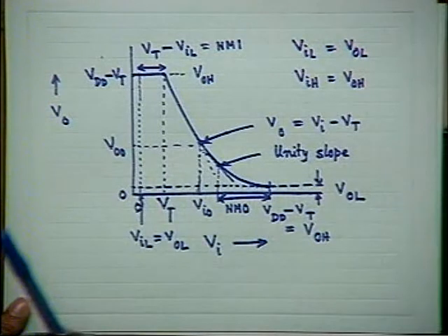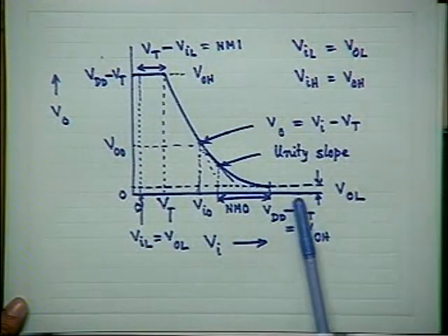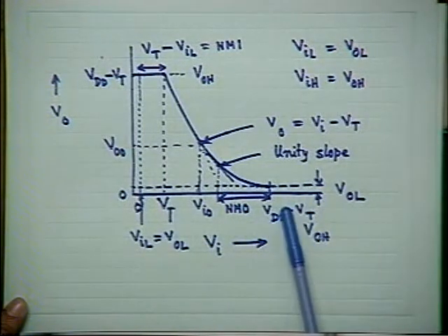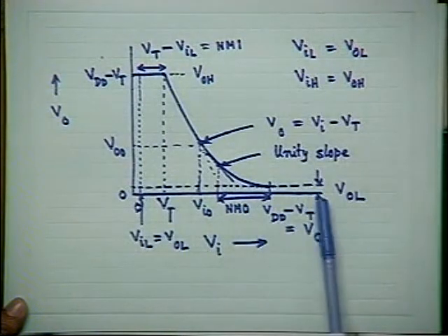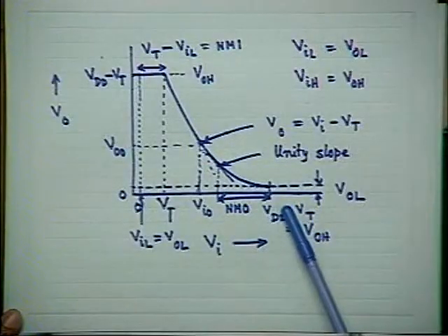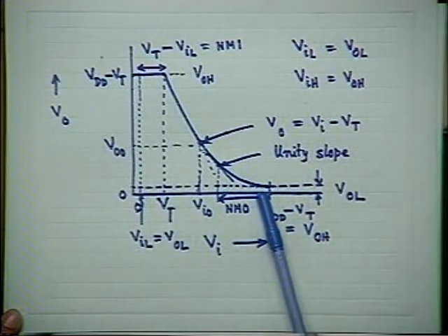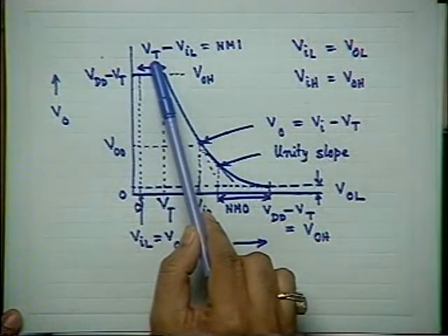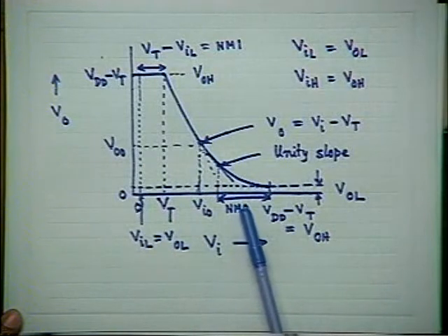you see that there is a little reverse thing. If your Vt is large, you are unnecessarily eating off some portion of the output swing. Where otherwise, I expected the output swing to go up to VDD. The output should go up to VDD, but it cannot go up to VDD in the NMOS configuration. It goes up to VDD minus Vt. Increasing the value of Vt will lower that, though it will improve the noise margin 1. It will deteriorate, degrade the value of NM0.